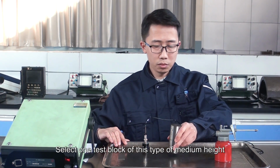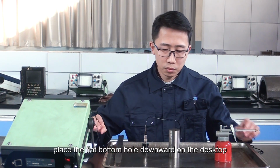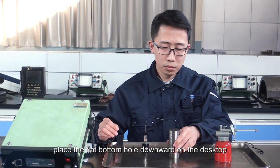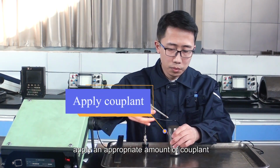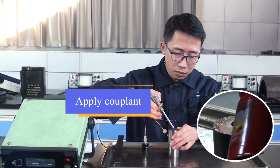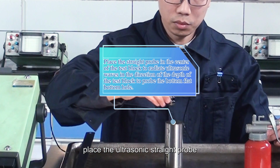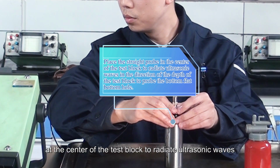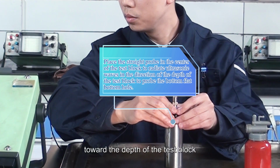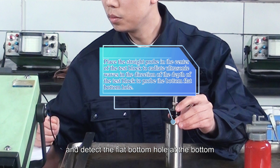Select one test block of this type of median height. Place the flat bottom hole downward on the desktop. Apply an appropriate amount of couplant on the testing surface. Place the ultrasonic straight probe at the center of the test block to radiate ultrasonic wave toward the depth of the test block and detect the flat bottom hole at the bottom.